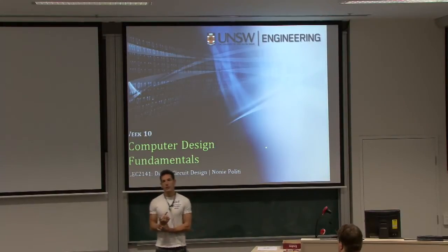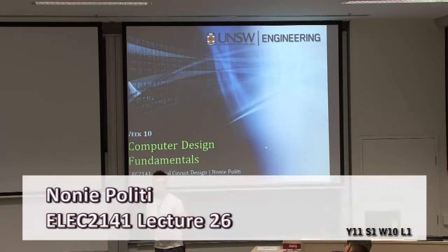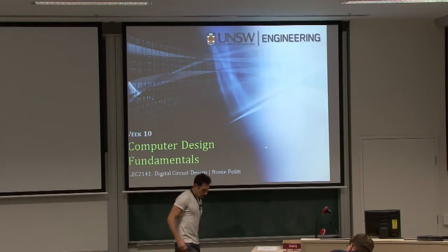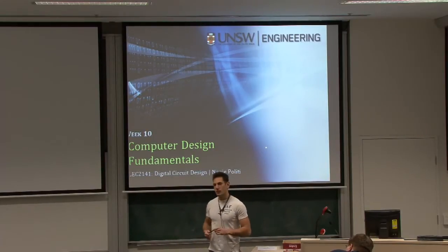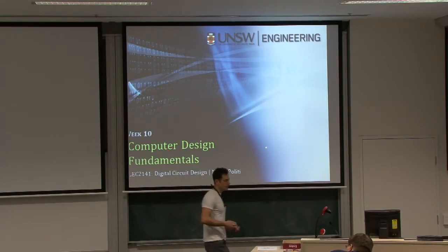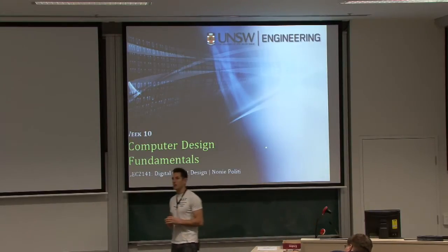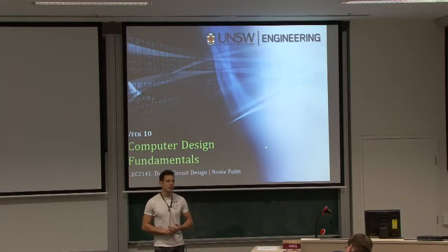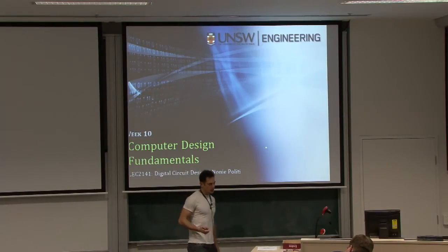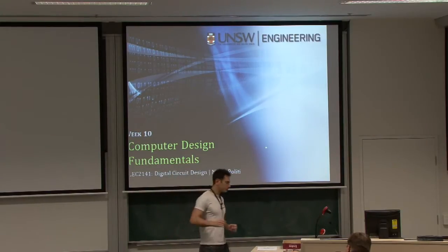Last week we started talking about arithmetic circuits. We presented the simple adders, and then the half adders and the full adders. We connected them together to make multi-bit adders. Then we talked about how we represent signed numbers in binary, so we can now represent both positive and negative numbers, which is how we took our adders and made subtractors out of them. And we said this will be the very basis of the arithmetic logic unit in our computer, which is what we will talk about today.